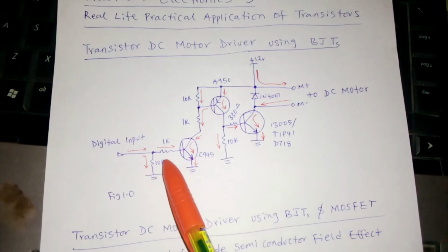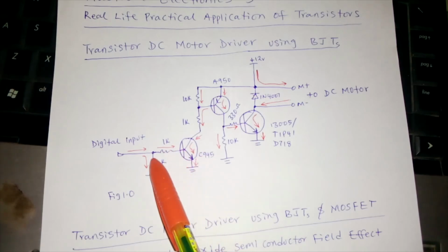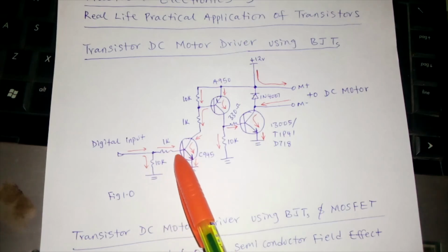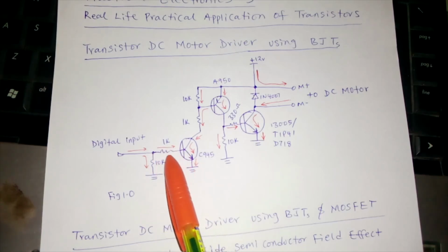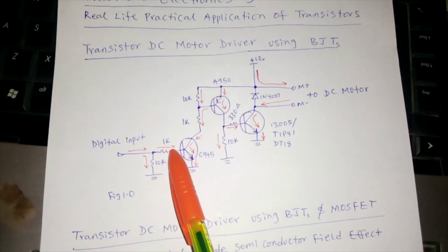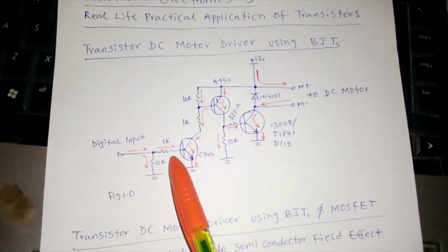At this point, we don't want the transistors to be conducting. So from this arrangement here, this 10K resistor is going to bring the base of the transistor to 0 volts, so there will be no voltage, so that it won't be floating. Then here we need a base resistor. You know, from our previous practical, you don't just connect signals directly to the base of the transistor without a current limiting resistor.